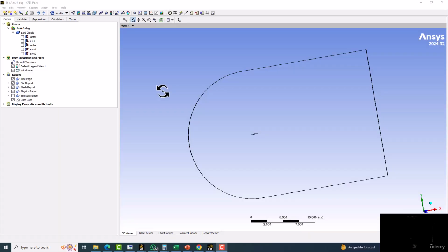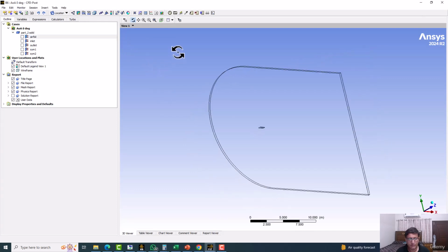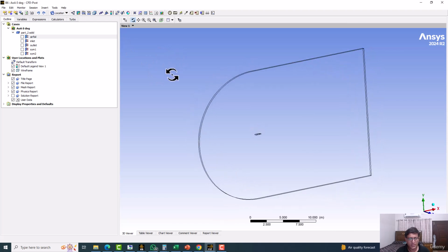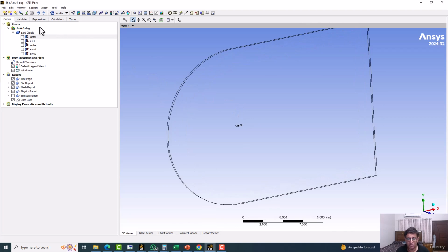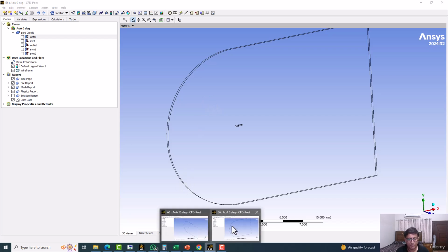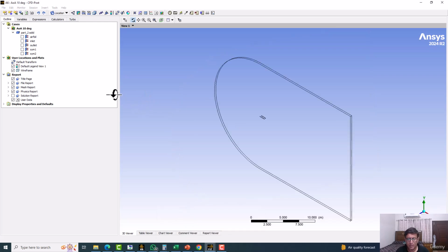Thank you. Okay, in this video I've explained how you can get the drag and lift coefficients in CFD Post. So first thing is that if the angle of attack is 0, then there's no need to define a new coordinate frame. If the angle of attack has some value, then you have to define a new coordinate frame. Okay, so how can this be done?